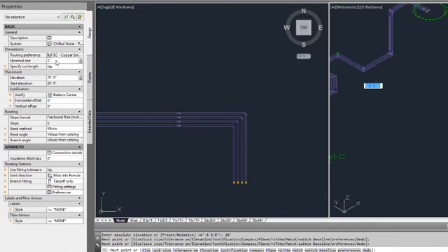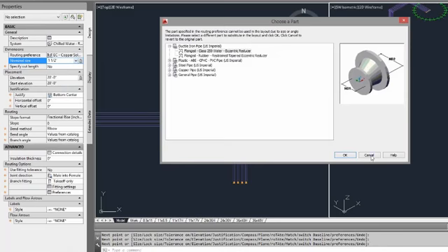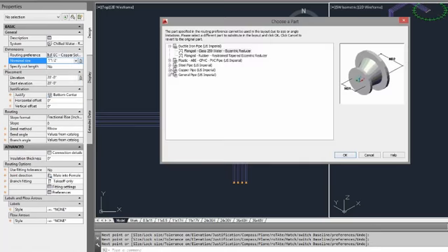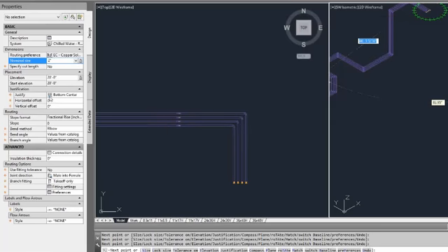And this rarely happens, but if the pipes need to change size, and let's see, this routing preference doesn't have a good reducing coupling set in it. So let's just come down here and get a, oops, see it's asking me for an eccentric coupling, and the reason why it's doing that is because justification is set to bottom center.